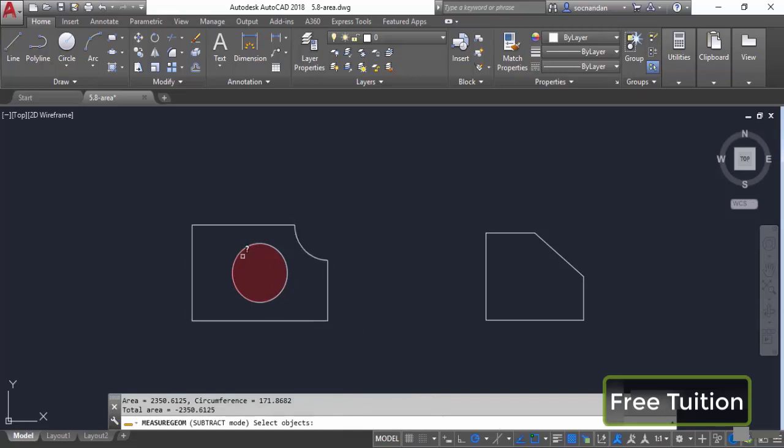Now you'll see that the color of this circle is different, and whenever you find the complete area, the area of this circle will be removed from that. Now press enter. Now go to the command line and select this add area option, and once again click on object and select this object. So now the final area can be seen here.